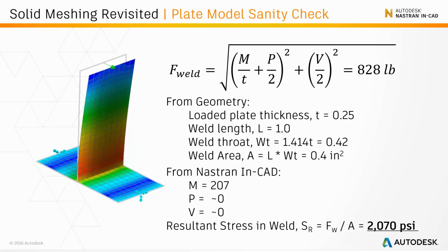In each of these cases, we get to the same place. We effectively end up with the same result. But using the plates and force method, we've done three things. We've, one, saved a significant amount of time in modeling. We've, two, saved a lot of calculation time in solving the model. And three, we're still able to achieve a reliable answer at the end of the day.